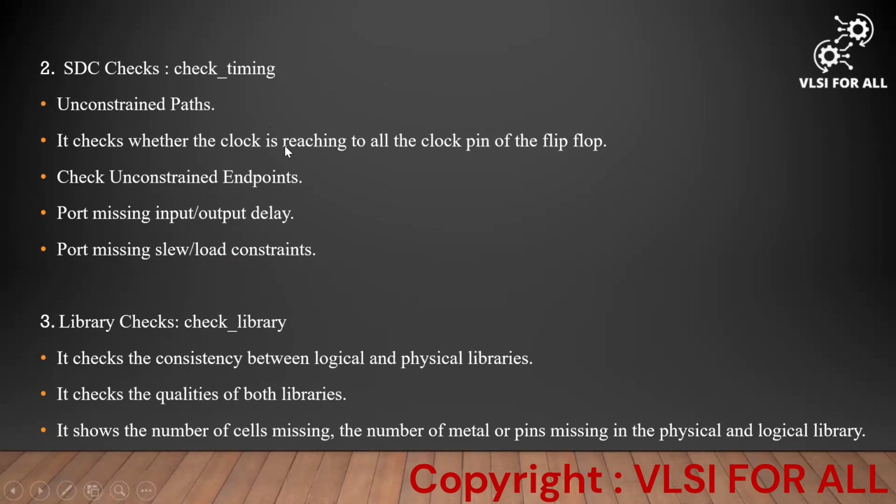And it checks whether the clock is reaching all the clock pins of the flip-flops. So you have to check what all the flops in our design are. The clock should reach the clock pins of all the flops in our design. So it will check that with this command.